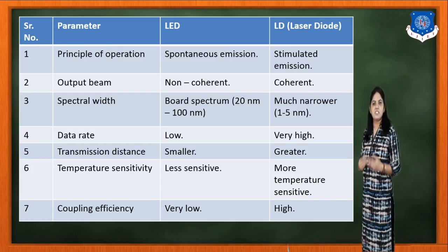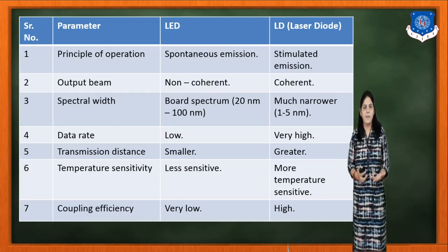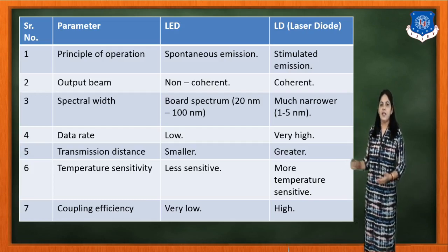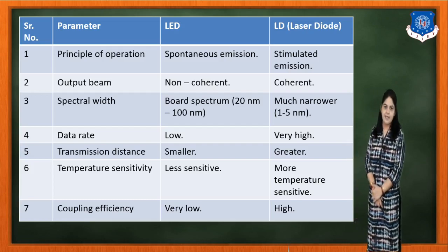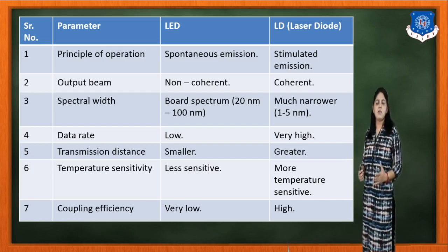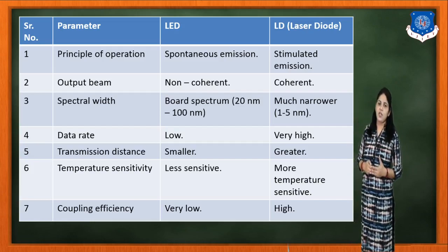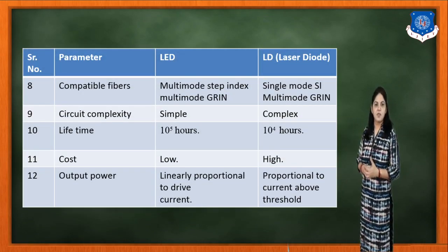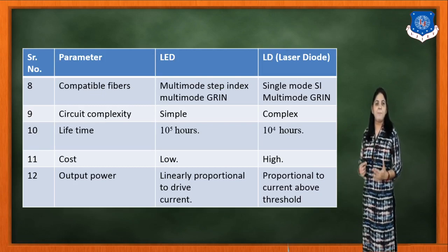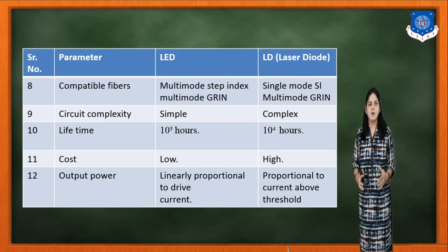About temperature sensitivity, the LED is less sensitive to temperature, and the laser diode is more temperature sensitive. The coupling efficiency in the case of the LED is very low, and in the case of the laser it is high. Compatible fibers: multi-mode step index and multi-mode graded index fibers are compatible with the LED.